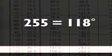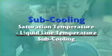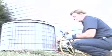To get the liquid line temperature, attach an insulated temperature probe on the liquid line leaving the condenser. Then plug the numbers into the formula to get the subcooling temperature. In this case, it's 20 degrees. Record the subcooling on the invoice as well. The system's superheat and subcooling are in the design range, which means it's now cooling as it should.